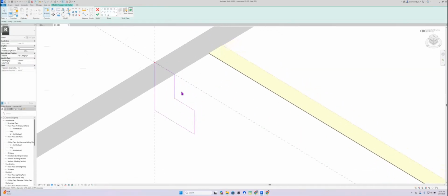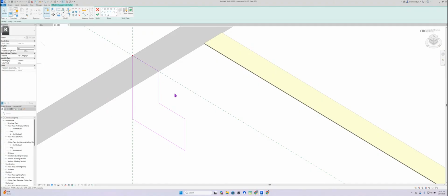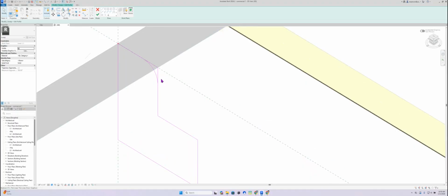Before I finish this, the fillets are not as easy as in AutoCAD, so I'm going to use a little circle of 2 inches. Here I'm going to use Revit's Start-End-Radius Arc, so I can go from quadrant to quadrant, and Revit will help me make the perfect circle. Then I need to trim carefully the arc and the piece of the line that I want to keep.